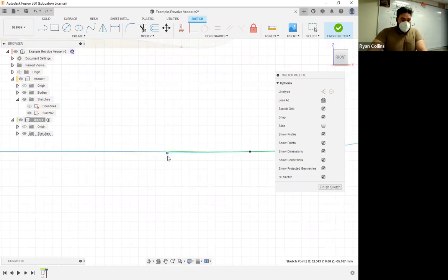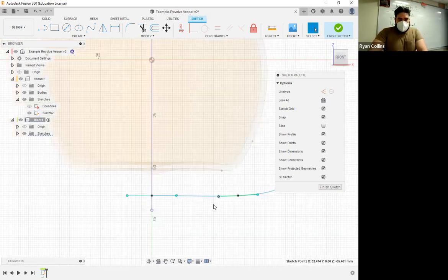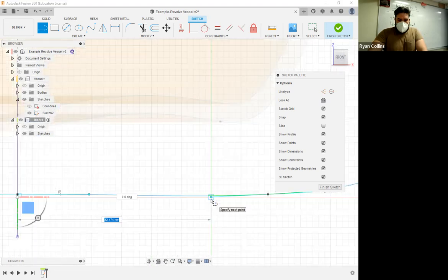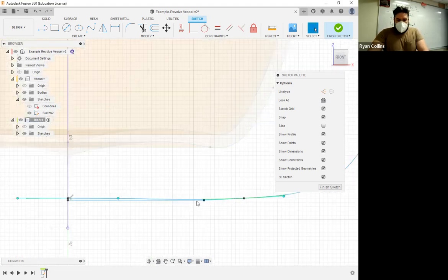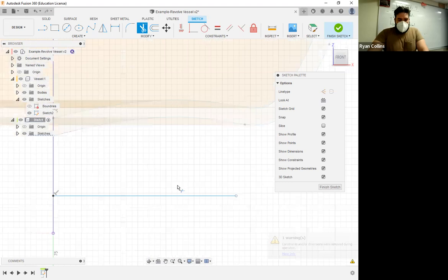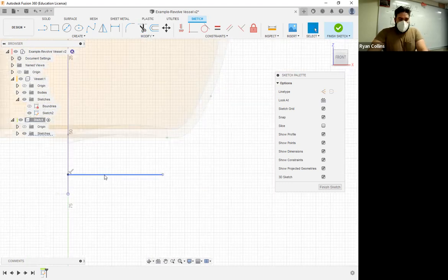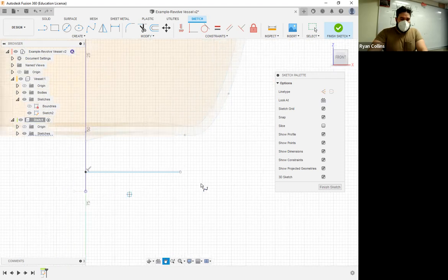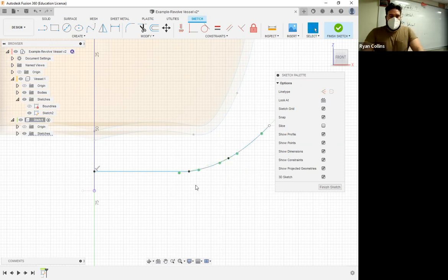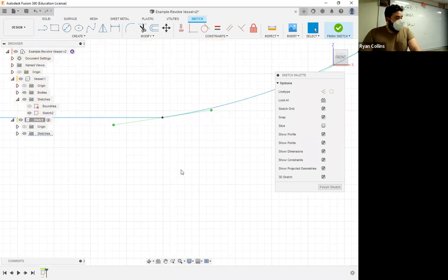Ultimately, if you want to make sure this is absolutely flat, don't use a fit point spline, use an actual line. So if I do that instead, line from there, straight over. Now I go in and trim that first one. Oh, I cut the whole thing off. That's okay too. That is a flat line. Now I can instead start from that flat line with a fit point spline and draw upwards, and I have my handy dish.